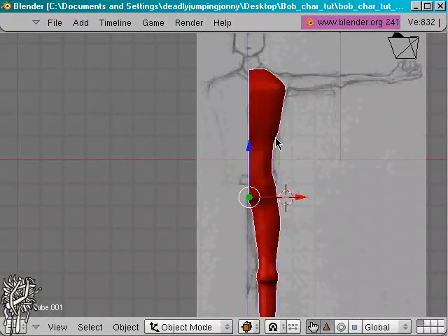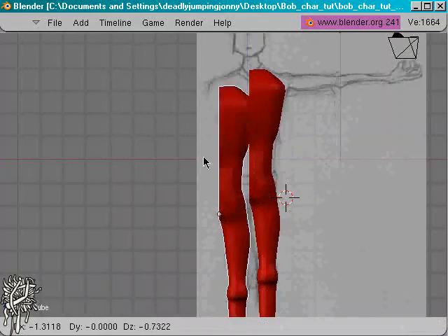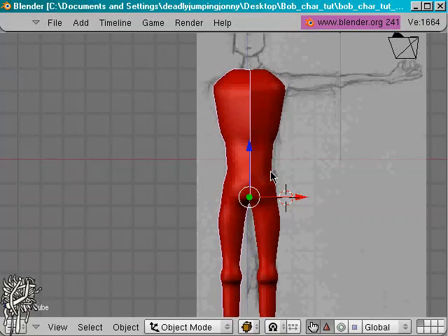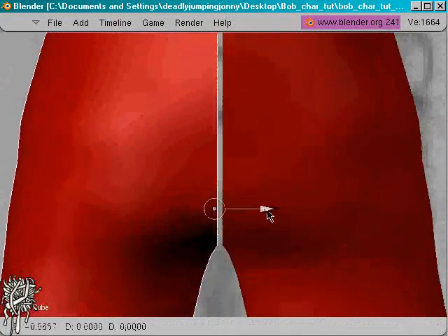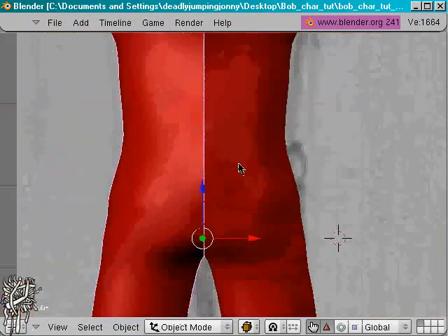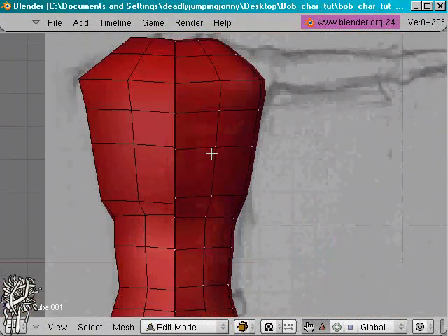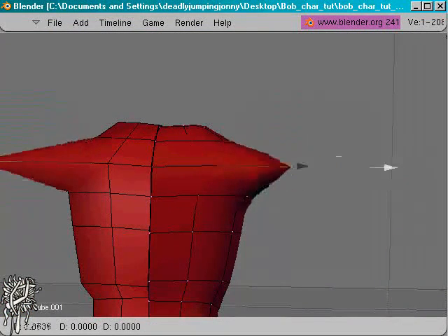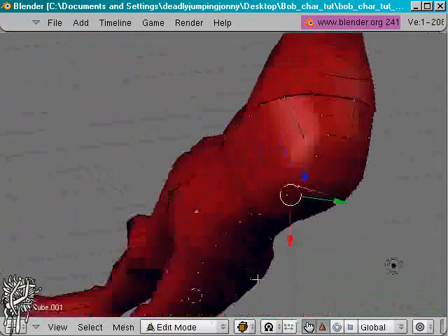Out of edit mode and into object mode, and instead of pressing Shift D like we did last time, which created a separate duplicate mesh that we joined up, this time we're going to create a duplicate mesh that shares the same data as the one we're actually modelling on, so it's more like a real-time mirror. Very handy. So Alt D instead of Shift D, and we've got a duplicate again. Right click to cancel the moving operation, scale on X by -1, and that basically mirrors our object. Move it along so it doesn't overlap so much. Not that it's very important right now because we're not joining them. And you'll see when we go into edit mode, the meshes will move as one, or alter as one as we do our changes.